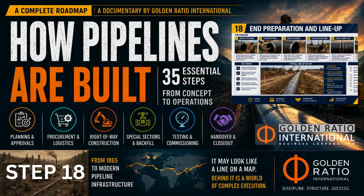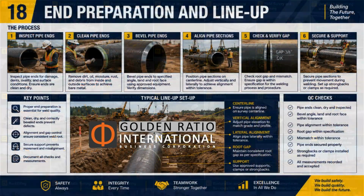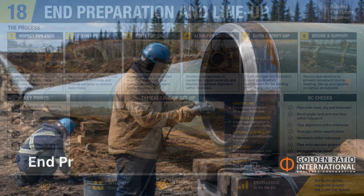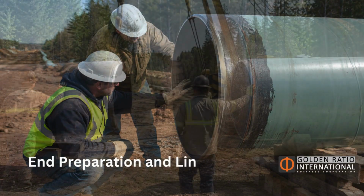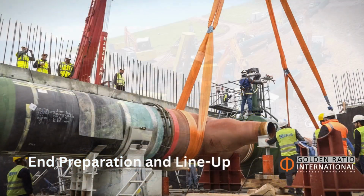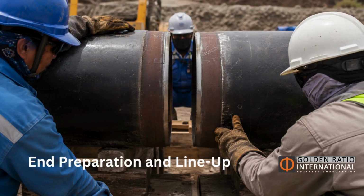End preparation and line-up. Before welding begins, the pipe ends must be prepared. End preparation may include cleaning, beveling, grinding, inspection, and removal of any condition that could affect weld quality. The line-up crew positions the pipe joints and aligns them correctly for welding, using clamps, supports, spacing, and alignment controls so the weld can meet specification.